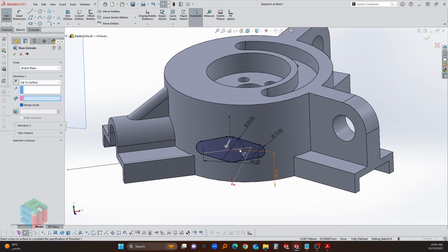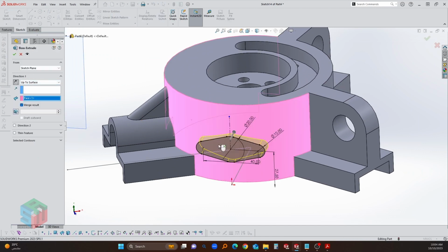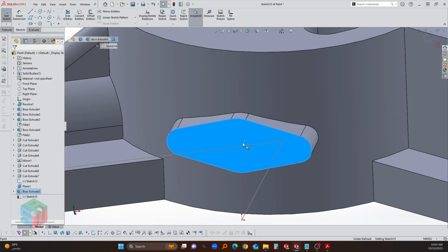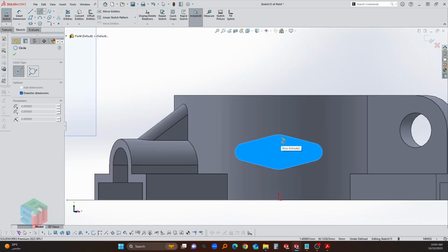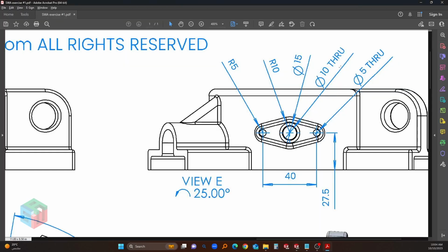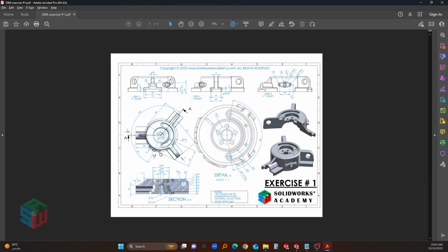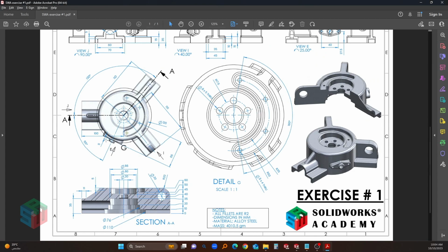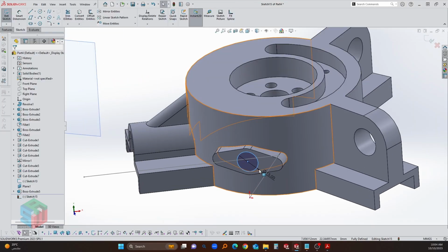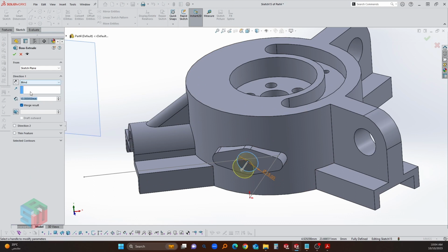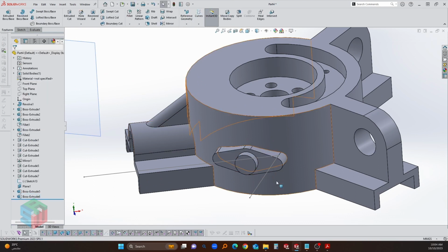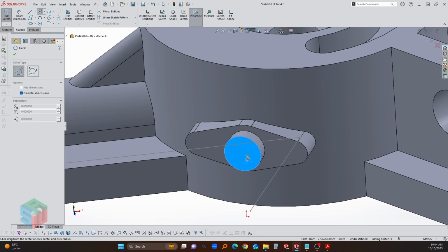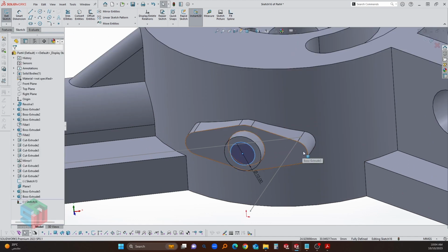And I'm going to extrude up the surface and choose that surface. I'm going to use this face again to make this smaller circle over here. It's diameter 15. Yep. And it extends 5 millimeter. Okay, 5. I'm gonna use this sketch to make a hole in the middle of this one. I guess it was 10 millimeter, and I'm gonna use those holes too.